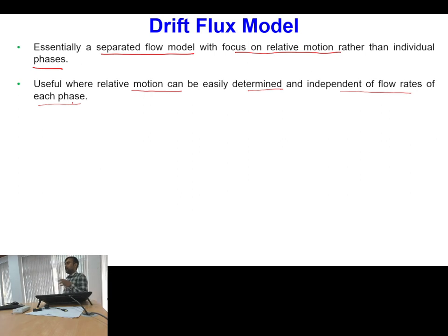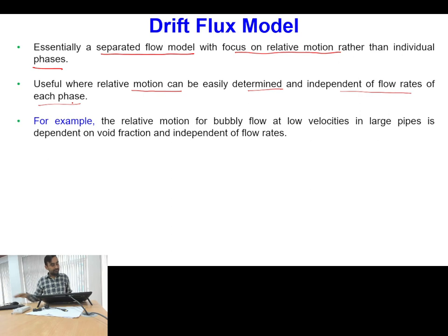Between the rising bubbles and the liquid, which moves in the downward direction to replenish the space vacated by the bubbles, that relative motion will give you some idea about the flow dynamics, and some idea about the void fraction present in the system. In that type of scenario we can use it. There is as such no bulk motion of the fluids.